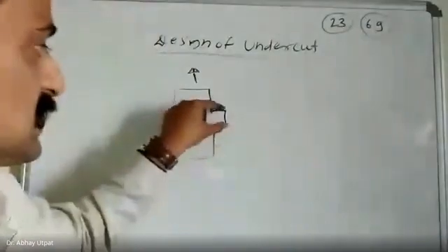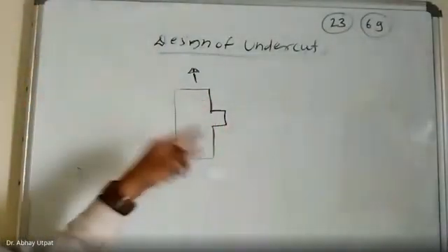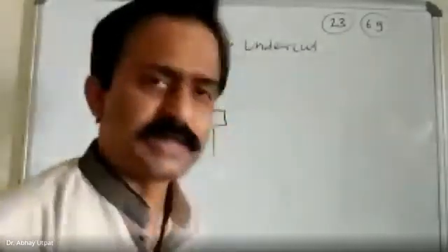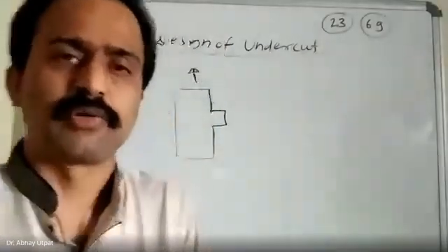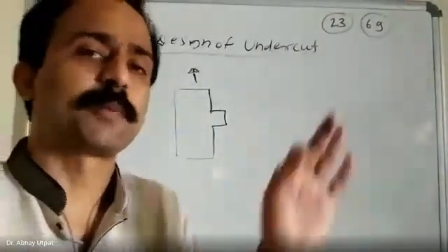So in such a case, if some undercuts are there, you can strip it for removing purpose. Undercuts are nothing but the obstacles or extended parts in the work component or your workpiece which may cause difficulty in removal with the help of the ejector pin.